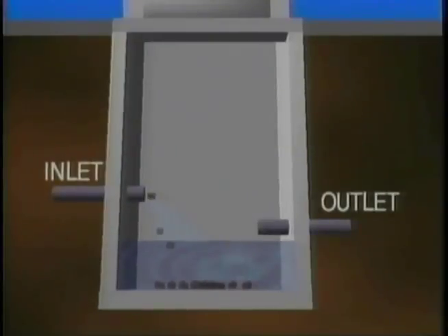The use of a sump keeps the sediment at the bottom of the basin so water can flow freely. If no sump is installed, sediment could plug the basin and the pipe could require cleaning more often.